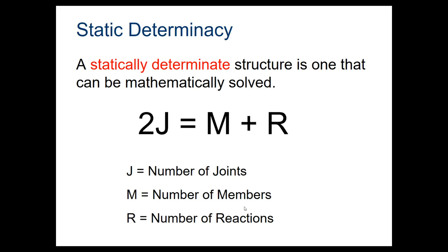And the reason why it's going to be 3 is because that pin joint has 2 forces. We said because it's preventing motion in 2 directions, the X and the Y, horizontal translations and vertical translations. That is 2 reactions, 2 forces. And then the roller joint has 1 because it is supporting the direction in 1. And neither one of them are restricting rotation, so we don't have any kind of moment to worry about. So when we talk about number of reactions, we're just really adding up those support forces. And again, for most of every bridge we do, that total should be 3.